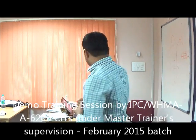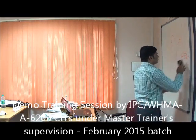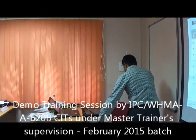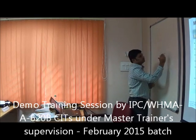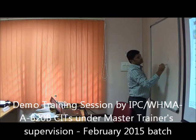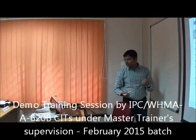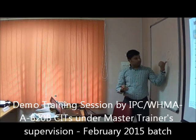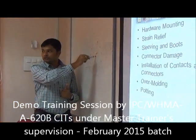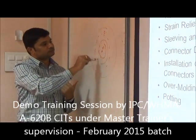If the insert arrangement is circular, if the pin starts at A, maybe it is Z. So make sure the insert arrangement for this type of connector is such that the first wire should be inserted at the starting point A, which is the center of the connector, and follow the clockwise.